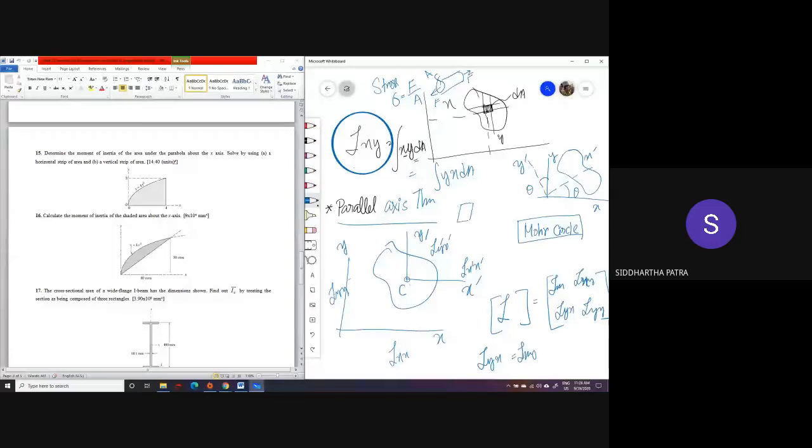Instead of assuming a cylinder, imagine a parallelepiped, and it could be stressed in all the three directions. And it could not just be under normal stress, but also shear stresses, 2 in each plane. So there are total 9 components of stress. Okay, and stress kind of looks like a matrix. So sigma xx, sigma xy, sigma xz, sigma yy, sigma zz, sigma yz. Okay, and symmetry. Symmetric bottom triangle.